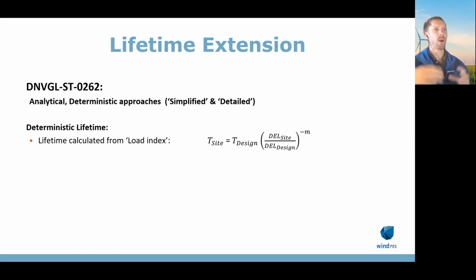So what is the relation between load index and lifetime? And this is what I've given here. So it's relatively simple, albeit a very nonlinear relationship. This ratio here, the damage equivalent load for the site divided by the damage equivalent load representing design, this ratio is the load index.